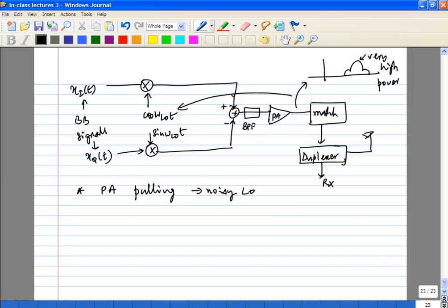Yes, it is a parasitic feedback, right? You ideally don't want a feedback. So it is actually a parasitic feedback through either an EM path which you should be modeling, or through the substrate, which again you should model, which is why people tend to try to model as much as possible, because you want to model all of these things. Some of them can be, some of them cannot be.